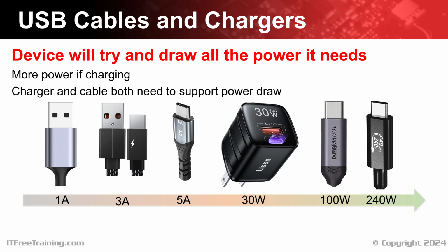In certain instances, this might suffice to keep the laptop operational without charging the battery. This workaround can be useful when you urgently need to use the laptop and do not have access to the appropriate charger. If your cable is a cheap cable, drawing too much power will cause the cable to heat up and become damaged. When the cable starts getting damaged, the power draw will be reduced. This is why cheap cables will charge better when you first purchase them and will become less effective as time goes on.